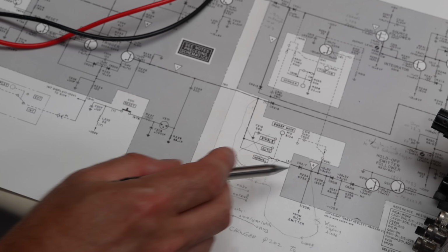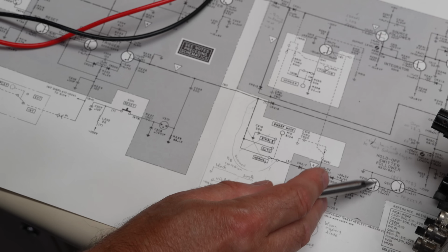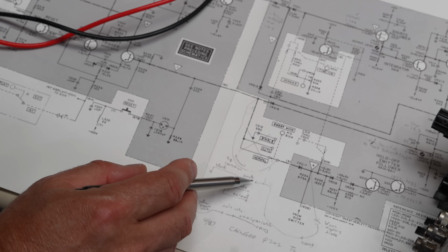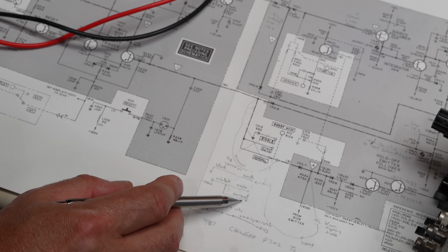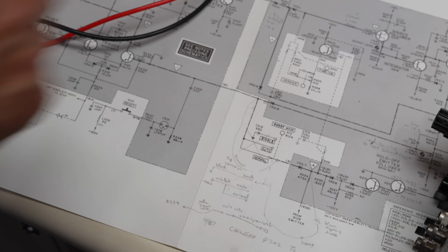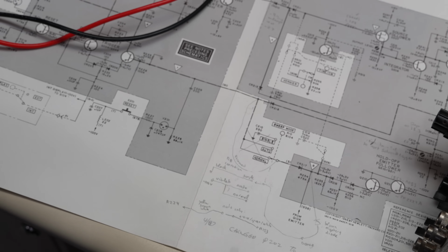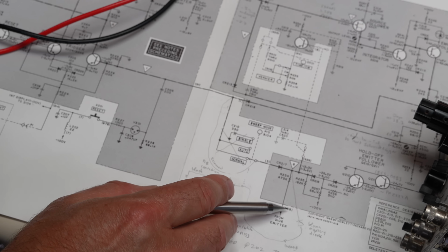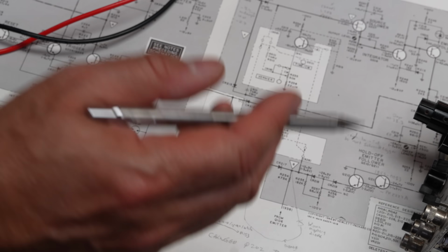Oh man, talk about the Swiss cheese thing. So the short blew this transistor, and then it blew that diode, and then when I placed it back over here, it shorted my power supply. Gee whiz. So I think all I have to do is put a diode that can take 100 volts, a little bit more, over here in the right polarity, and I reconnect everything and that should work.